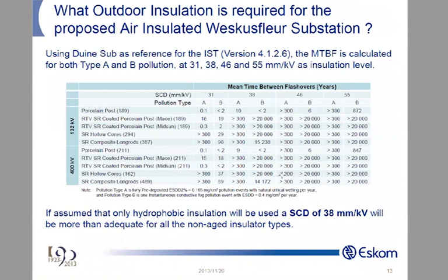Okay, so now with the coating, you must normally coat between 0.3 and 0.5 millimeters, not much more than that, because once the arc is moving around, the temperature of the arc is not only transferred and causes the alumina trihydrate to go, but the heat is also transferred into the porcelain and sunk into the porcelain. So it reduces the arc root temperatures. So you find that your erosion, or tracking and erosion, on the coating becomes far less.